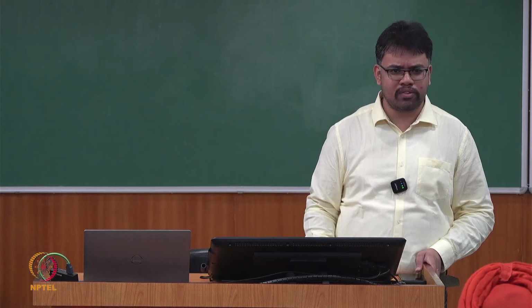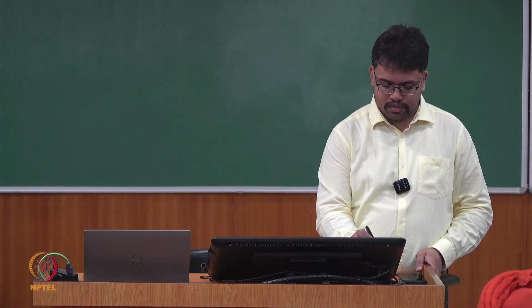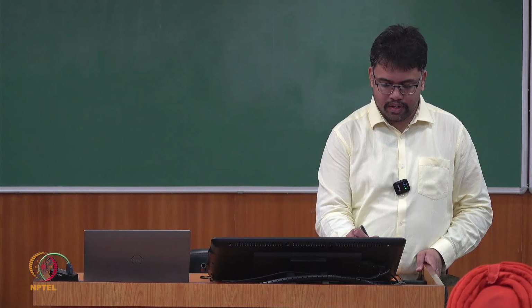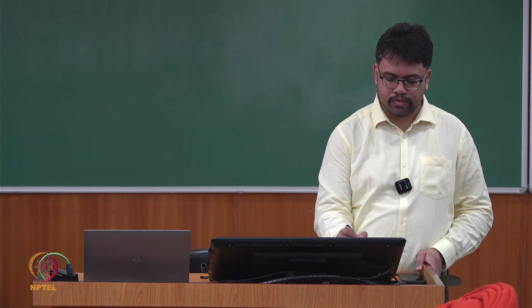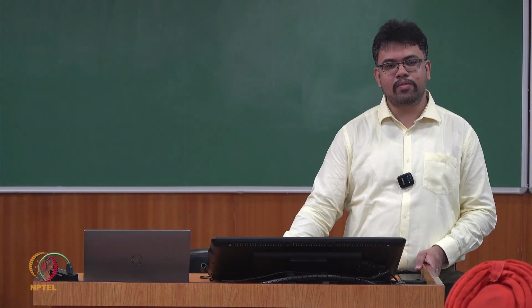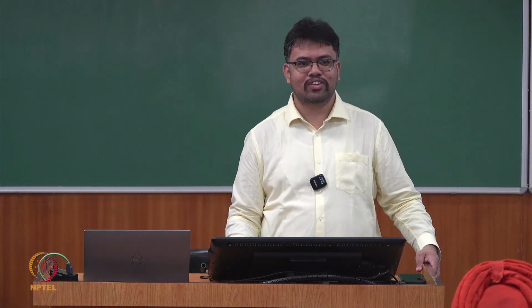Let's say it is all abundantly simple. EI del 4 W del x4 plus rho A del 2 W del t2 will be equal to 0. Okay. Will that be 0? Mass. Now if you see, there could be several ways of doing it. The mass is only at the right hand side, so how can we incorporate it into the domain equation?